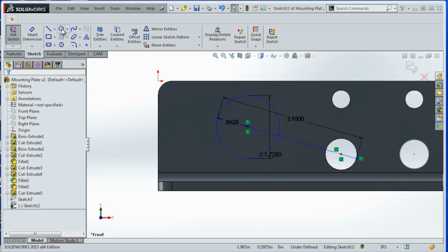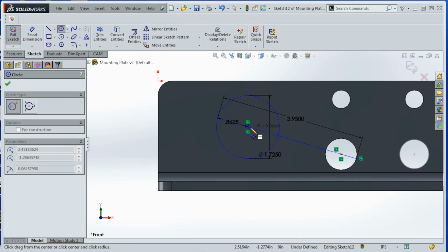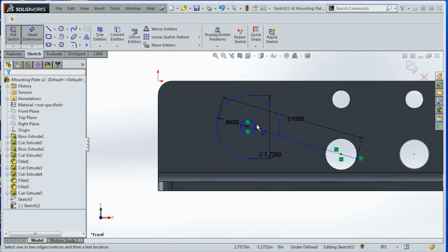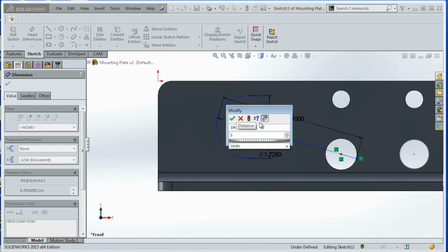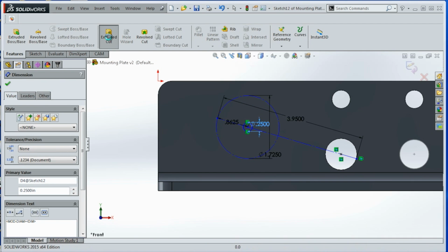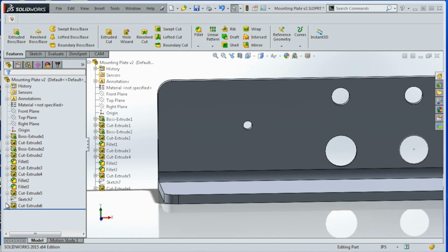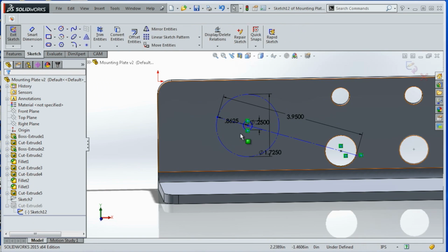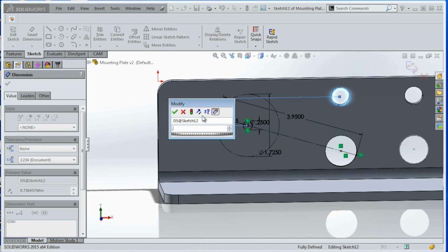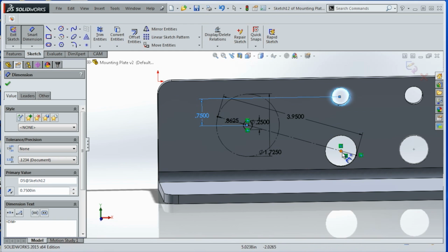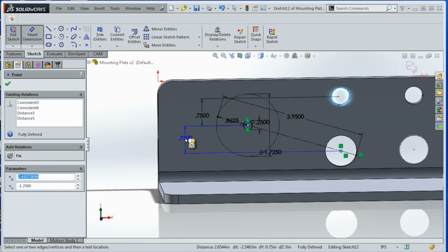And then what we actually want to do is just machine a 1/4 inch shaft through there. So that's what we'll actually do, is the cut. Features, extrude cut. Perfect. Now let's set the dimension of it so where we want it to. So let's say from there to there, we'll say 0.75, and I think that'll actually put it on center between those two. Yeah, exactly.